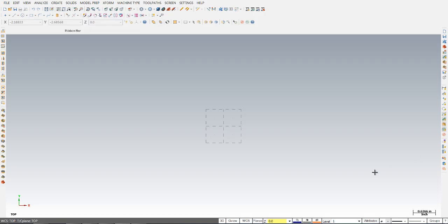Back to Mastercam, make sure that you're working in 3D mode and your Z plane is set to 0. Click on G View, change the construction plane to front. Then select your G View and change it to front as well. Click on Create, Rectangle. Specify a length of 2 inches and a height of -1 inches. Choose the origin. Select the OK button to exit the command.